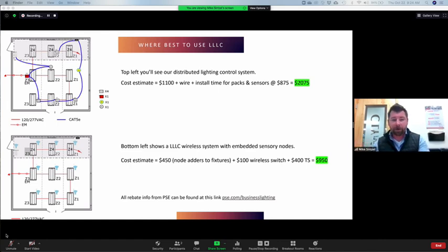I push that cart and it stops and it's getting reflection from the light. That photocell will sense, because it's a closed loop looking straight down, that reflected intensity, and it's going to dim that light down. So you'd have one light in a row of lights at a different intensity just because there's a cart right below it.